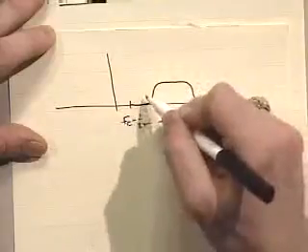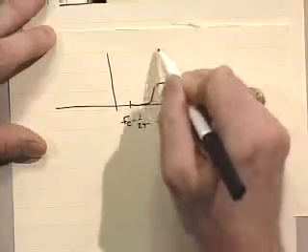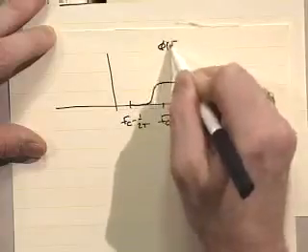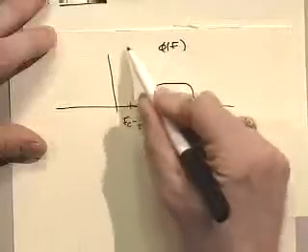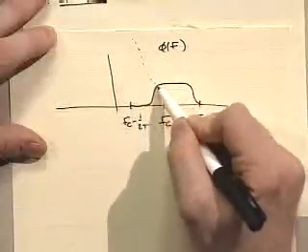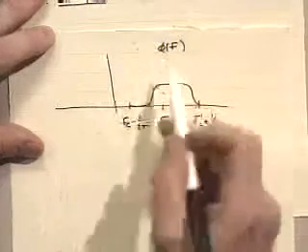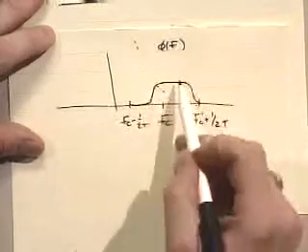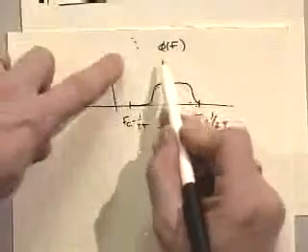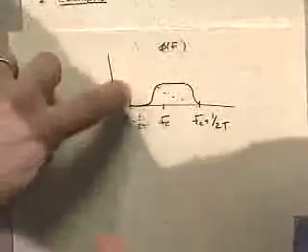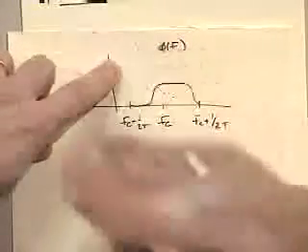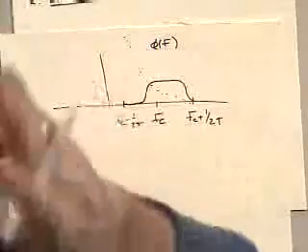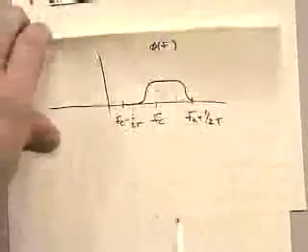What would happen is that the phi of f that you had tried to use to make this look flat, essentially, is going to have some kind of infinite. And unfortunately, when you try to invert this, if you make this a normalized basis function, then when you invert it, the gain is going to go down. The signal-to-noise ratio is going to go down in the channel. Or if you don't make it normalized, you essentially increase the transmit power. So not quite. Your intuition's in the right direction, but you've got to deal with the transmit power increase in that case.